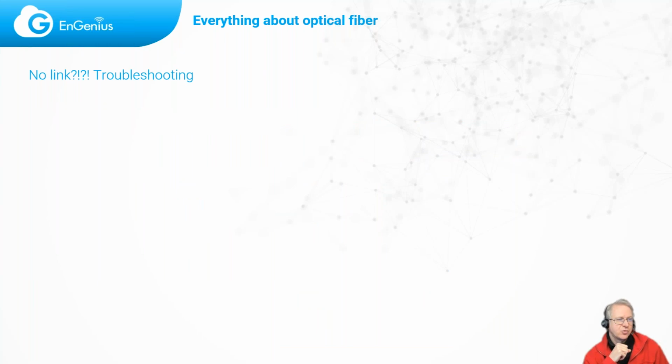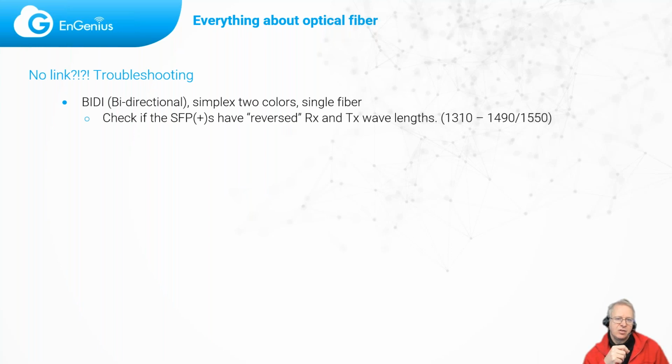So I have some troubleshooting things that I found. If you have bidirectional simplex single fiber 2-color modules, check that the one side and the other side are really reversed, that you have the correct pair and not both have the same values for receive or transmit. Because if they have the same values, then you will not be able to see any signal. If it's sending on the same color and is trying to receive on the other color on both sides, you will not get any data through.